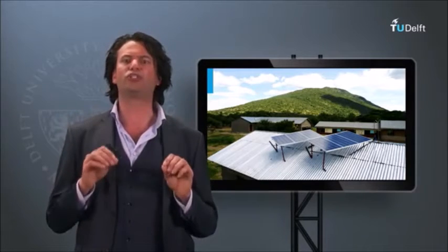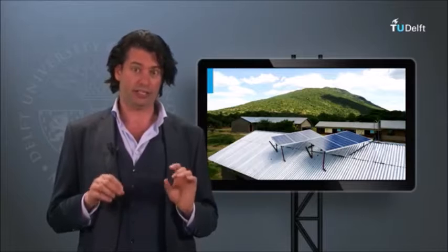So we have seen a simple method to design a standalone PV system based on the load requirements and available system components. Note that this is definitely not the most exhaustive way to design the PV system. This method works better for places with more or less consistent irradiance levels. For places with severe disparity between the summer and winter irradiances, the number of autonomous days would increase for winter and the system cost would consequently rise.